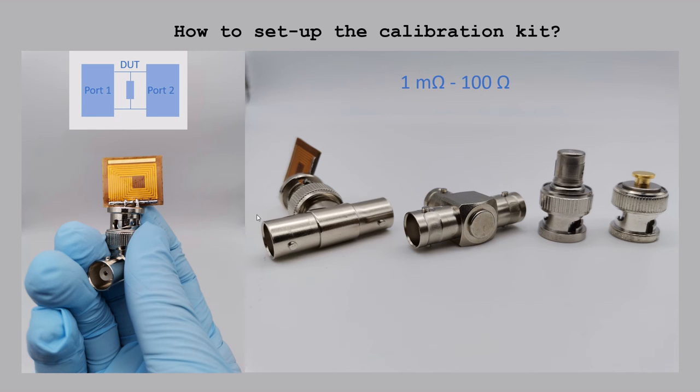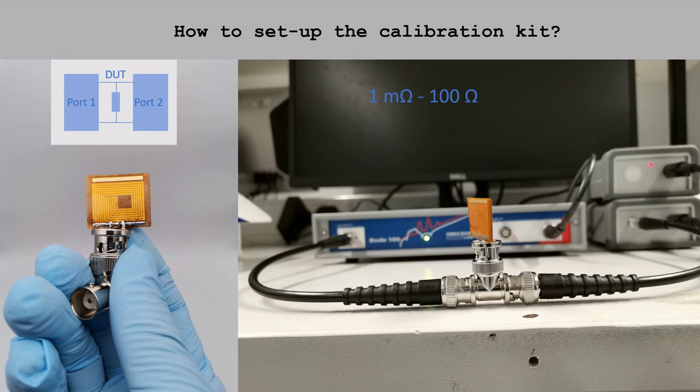Obviously, the impedance of this T-type connector must be calibrated, and here we can use the same T-type connector, the standardized 50 ohm resistor, and the standardized 0 impedance for the open calibration, the 50 ohm calibration, and the short calibration, so that the impedance of this T-type can be calibrated. After fully calibrating the T-type and the cables, our parallel inductors, whose ESR is only 7 milliohm, can also be accurately measured. And here is the photo of our test setup.